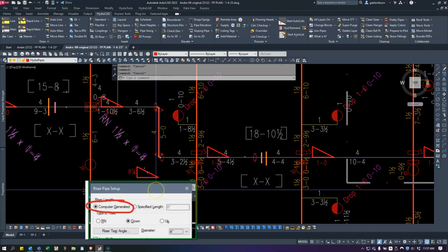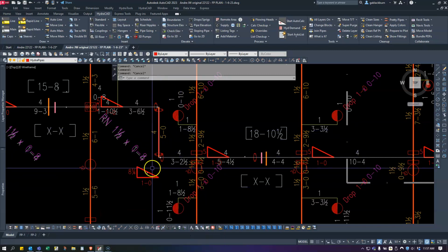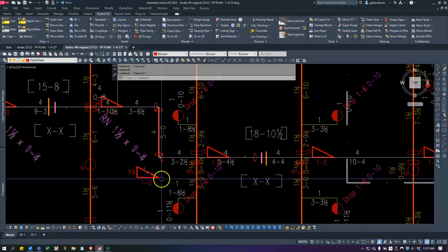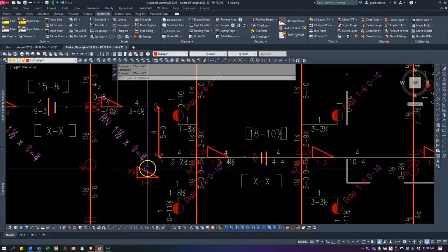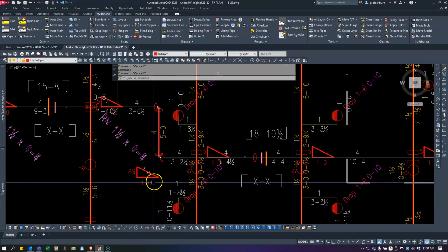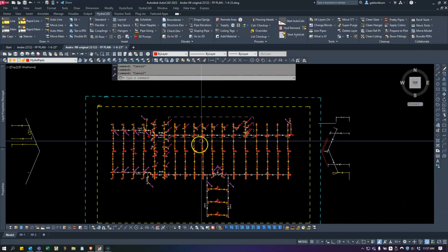In this case it's kind of similar. We're going from one elevation to a new elevation, but we're forcing the slope. We're not telling it to be computer generated. So initially, my thought is that maybe there's something wrong with this pitch, but let's figure it out, and let's use the walk model to make sure we're right.